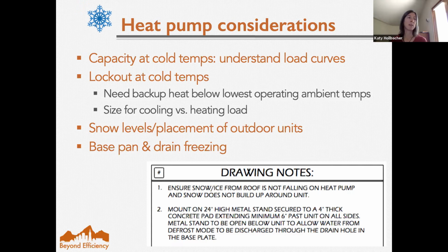But if you do have a multifamily unit, even in our cold climate, these units would likely be oversized if you have one indoor unit on, say, a 10 by 10 bedroom on the third floor of a building that only has one exterior wall and one window for heat loss. There's another dwelling unit above, another below, and living space outside of it. The load in that space is going to be quite low. So that's where these ducted units can be a really good choice. You can have just one unit that you would duct to these rooms. Absolutely a really good way to do it.